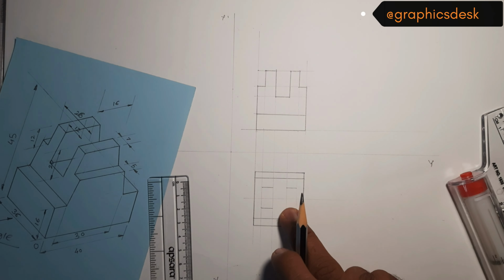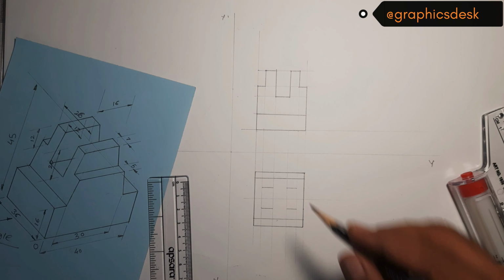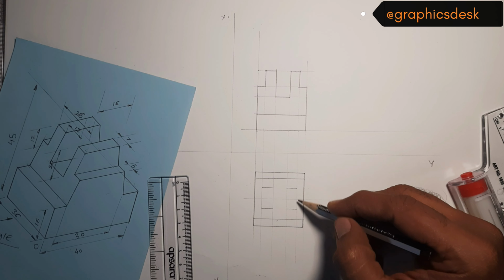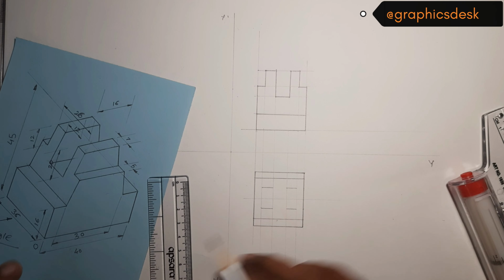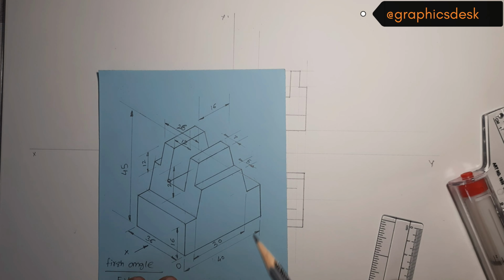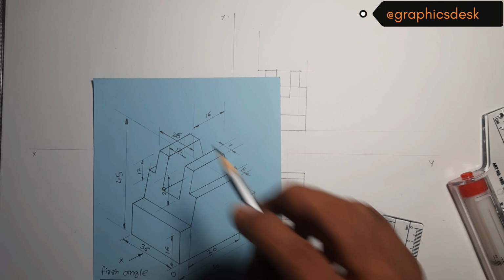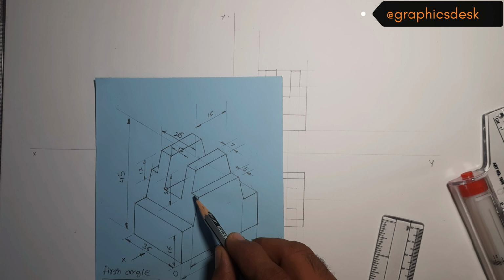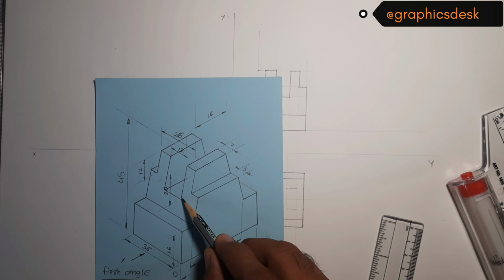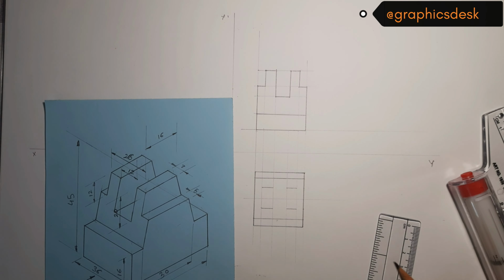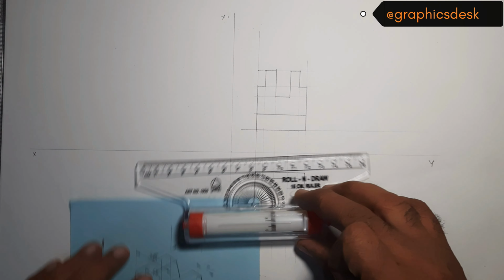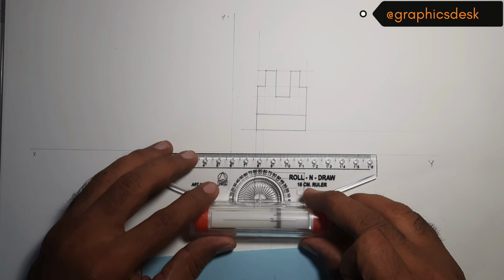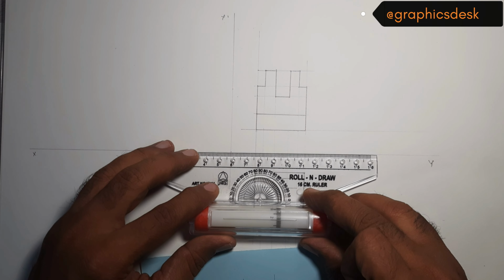Now I'm keeping it faint for now, because these faint lines would be made solid later on, because there are 2 projections that we have to carry from the side view into the top view, which essentially is for this one and for this one. So let's go to the RHS view now. Let's carry the horizontal projections first, and then we'll carry the projections from the top view.